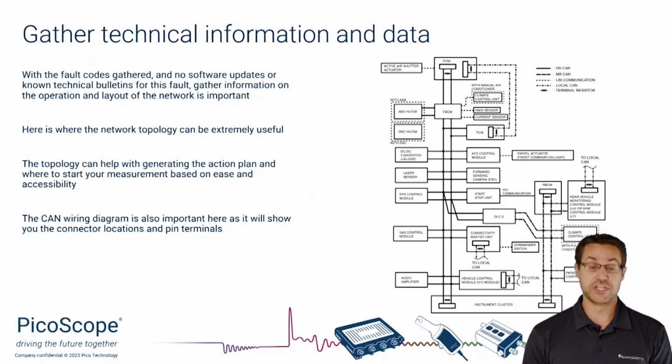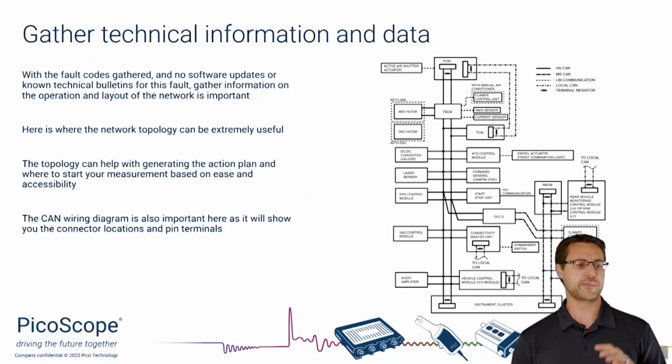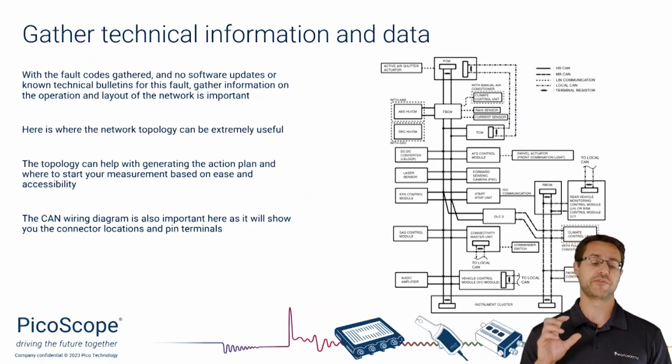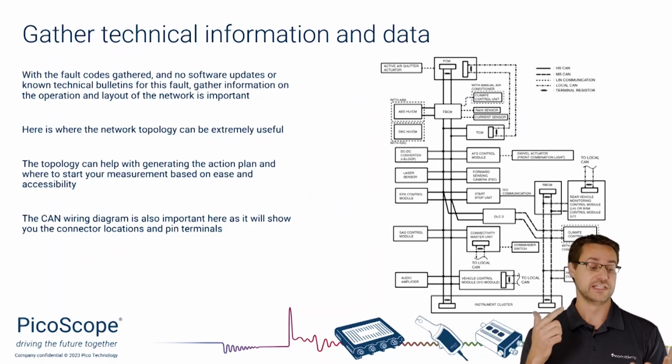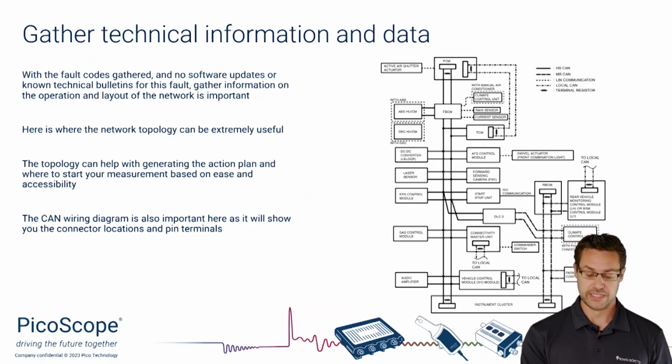Now, there was a number of fault codes that existed. A lot of them are all U codes, which indicates that it's a communication fault. A key bit of information here as well is that it's multiple ECUs reporting different losses of communication. So it may have been the engine ECU has lost communication with the ABS ECU, the instrument cluster, front radar, front forward-facing camera, etc. But then they would also report communication losses with those ECUs as well. So the instrument cluster would report a fault with the engine ECU, and so on.